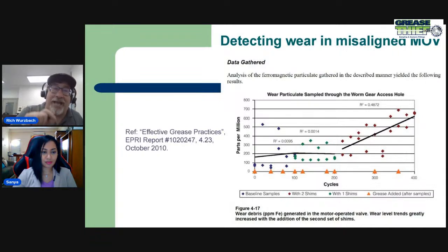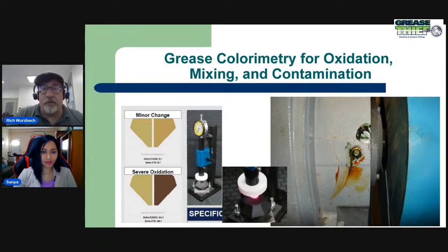And then secondly, as that increase in wear happens in the component, it is proportionally detectable in that properly taken grease sample. And that was a big question at the time. It's like, yeah, we can do grease samples, but we can't really shake it up like an oil sample. The particles may be all over the place. Who knows? But this really helped answer that question and said, no, if you take the right sample, you can see that. You can see the change. You can see the increase. And we're not talking about a lot here, just a couple hundred ppm, but really clear in terms of the rate of change and that parameter that we want to keep on top of there.